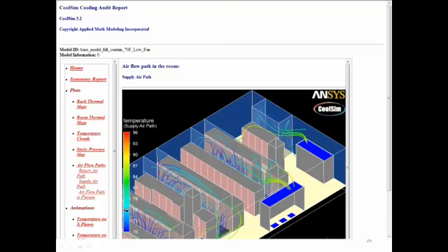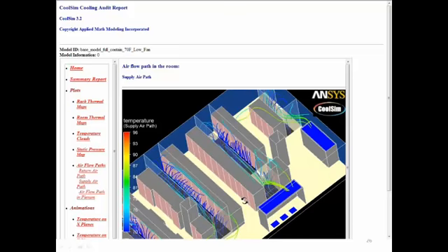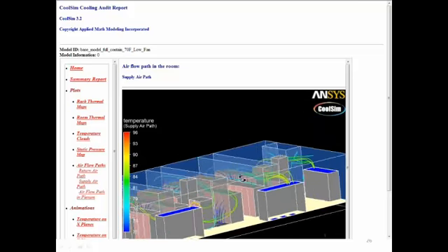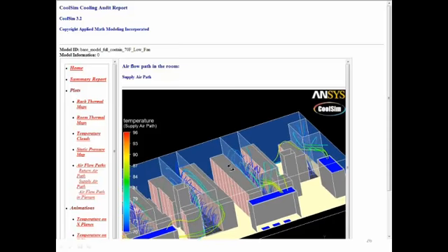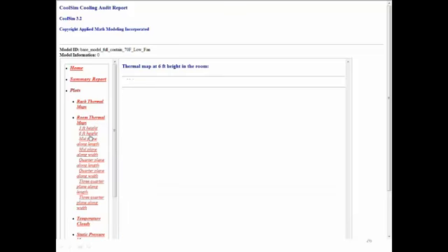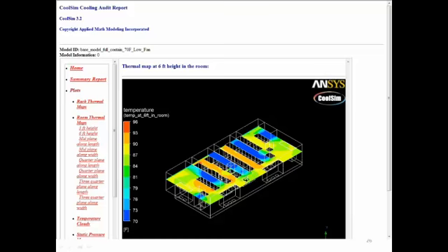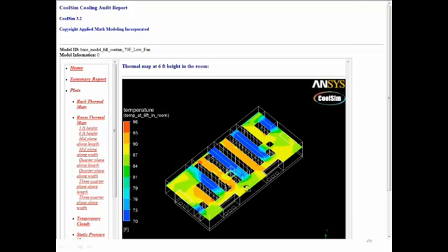The other thing I wanted to point out here is, I mentioned earlier, I like hot aisle better. And the reason I like hot aisle better is because people do get into this environment and have to work in this environment. If you take a look at the temperature in this environment due to the cold aisle and the 70-degree supply, you'll see here it gets kind of warm.